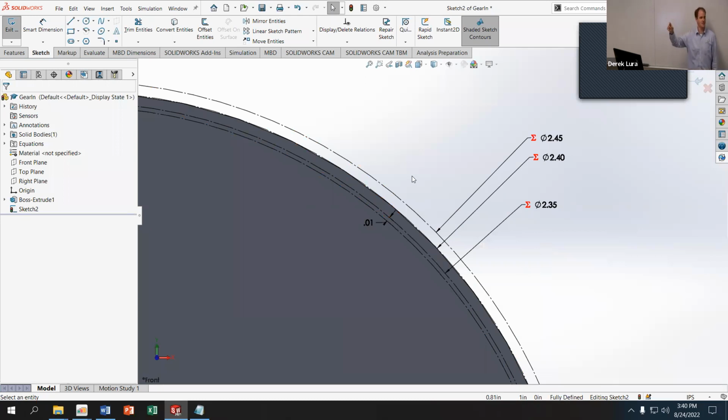And the reason I'm using plus or minus 1/2 of a pitch is it makes the height of the tooth proportional to the pitch of the tooth. And so the aspect ratio, the length to width of the tooth, will be reasonable. The height of the tooth and the pitch don't have to be the same. You could have longer, skinnier teeth, and you could have shorter, stubbier teeth. But if you start going to extremes on that, where your pitch and your tooth height are wildly different, it's not going to mesh because the teeth will hit each other, basically, right?